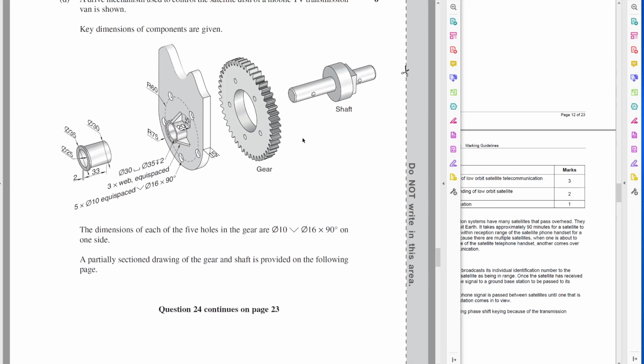I do talk about this in one of my videos. It's probably not great, but I do talk about it somewhere. And then we have some little features, we're going to call these webs or stiffeners, along here. We don't section those. If we do section them, we section them at half the spacing that we normally would. Right? I would say that we don't section them. My practice in engineering studies is you don't section them, ever.